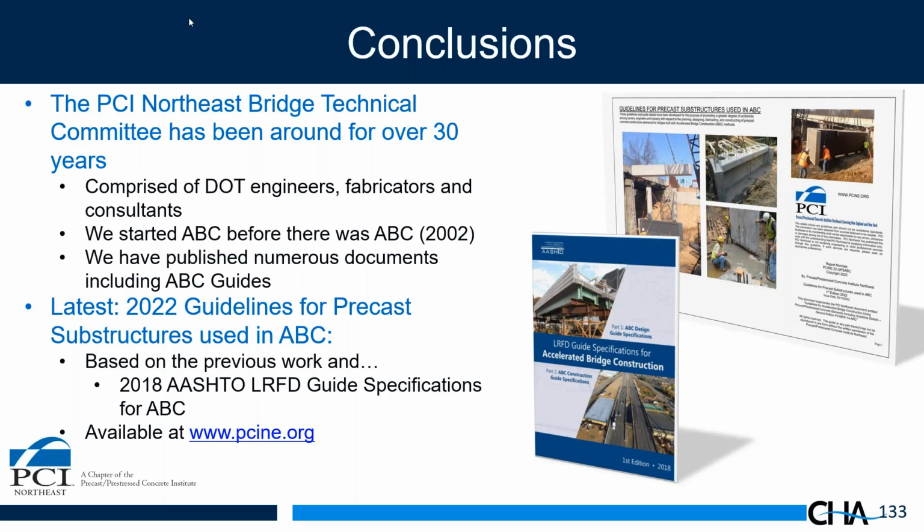can't see. Some states like Texas DOT have specified that the contractor has to build a mock-up, pour the grout into that complex void, and break it apart a couple days later to prove that they're getting the grout into the void appropriately. That's another option. But as I said before, a lot of the details we presented here today are not blind connections.